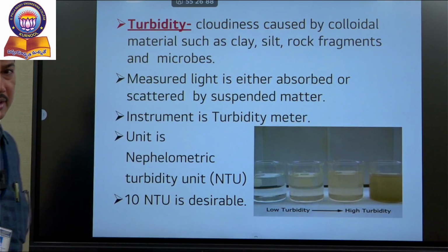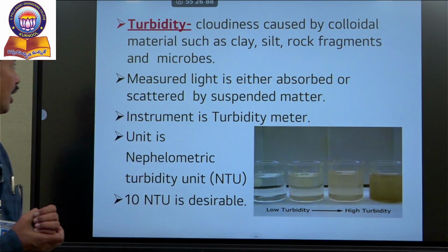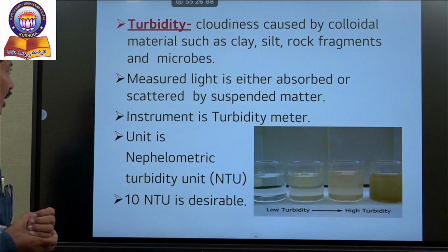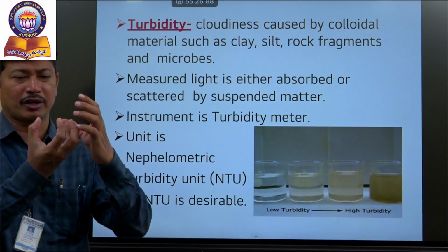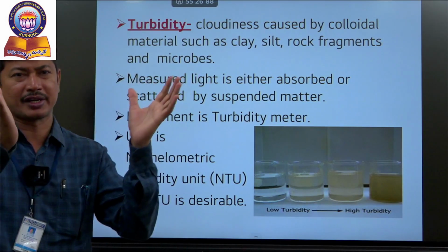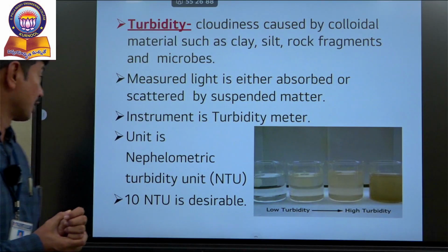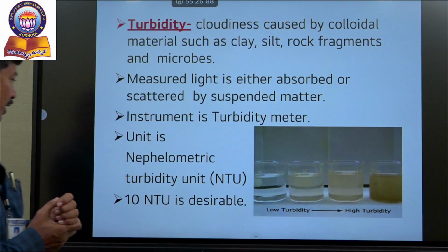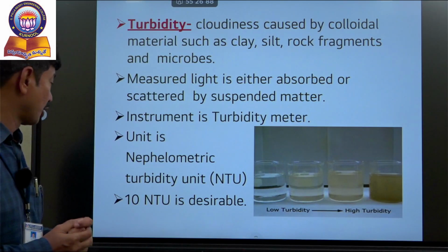And turbidity represents the presence of suspended solids, mainly due to the presence of clay, silt, and other rock fragments. The working principle is light scattering. Whenever light passes through the water, if any particle is present, the light touches the particle and scatters. The scattered light is directly proportional to the turbidity, which is measured. Generally NTU, nephelometric turbidity units, is used. The desirable limit is 10 NTU.